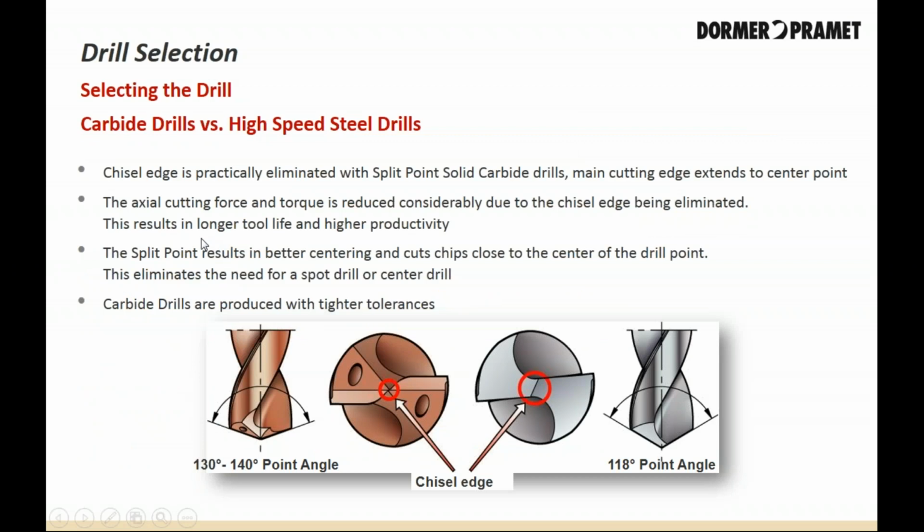Solid carbide drills versus HSS drills. Better machining tolerances. Solid carbide drills are stiffer and harder than HSS drills and will bend or flex much less. This enables them to machine to much closer tolerances. HSS drills will almost always drill slightly oversized and in many cases will require a secondary reaming operation in order to hold closer tolerances on the finished hole size.